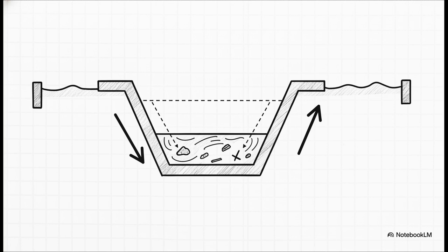That downward-sloping throat artificially increases the head difference between the upstream and critical sections, which makes taking your measurements so much easier and way more accurate. Then, that upward slope at the end produces a high tailwater depth, which cleverly reduces the length of the supercritical flow region. And because this unique geometry essentially forces a high-velocity rush of water straight through the throat, it safely flushes out all that troublesome debris we talked about earlier. It practically takes care of itself.